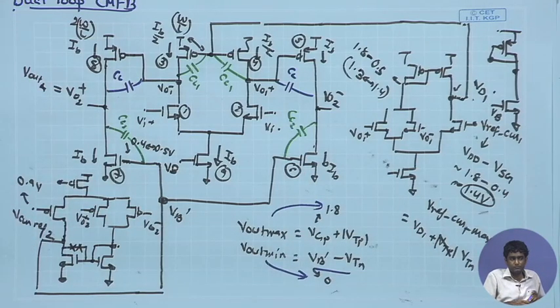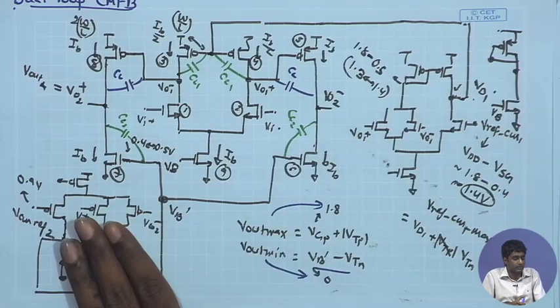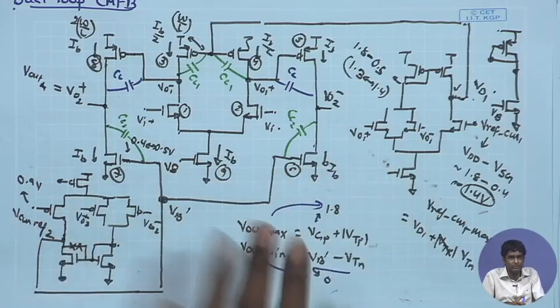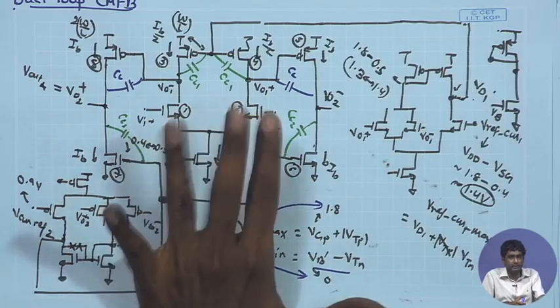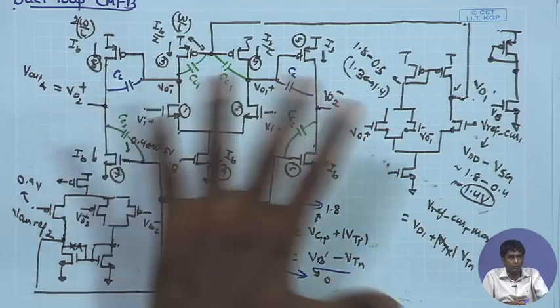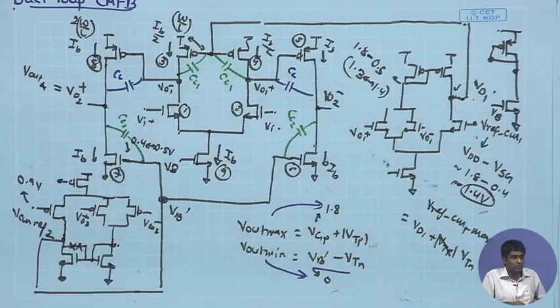Sir, from the simulation point of view, for the phase margin, we determine first CC1, then again CC and CC2. So, there are two different loops. CC1, CC2 can be pretty close. These values are just to stabilize these two feedback loops, and the amplifier configuration and bias currents are similar. So, they can be pretty close. CC can be different because of the bandwidth requirement. You can have a different pole for the differential operation as compared to the common mode operation.